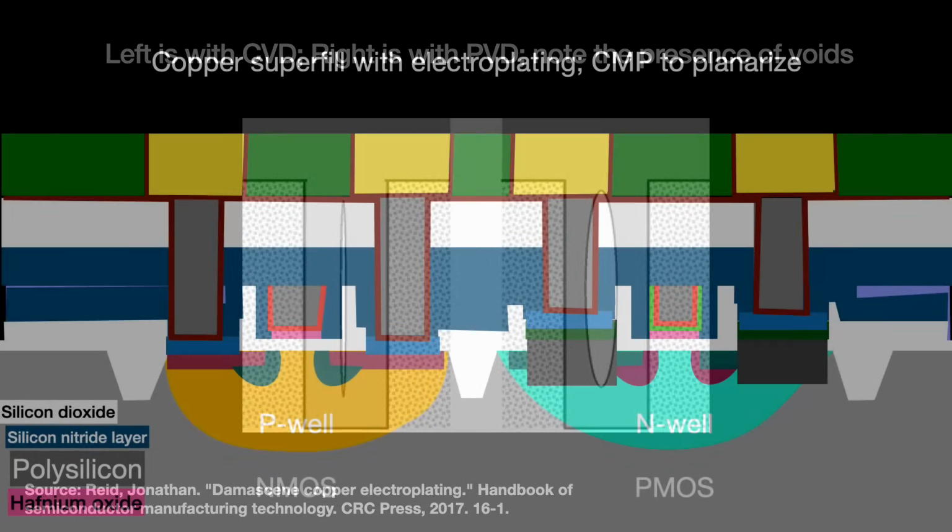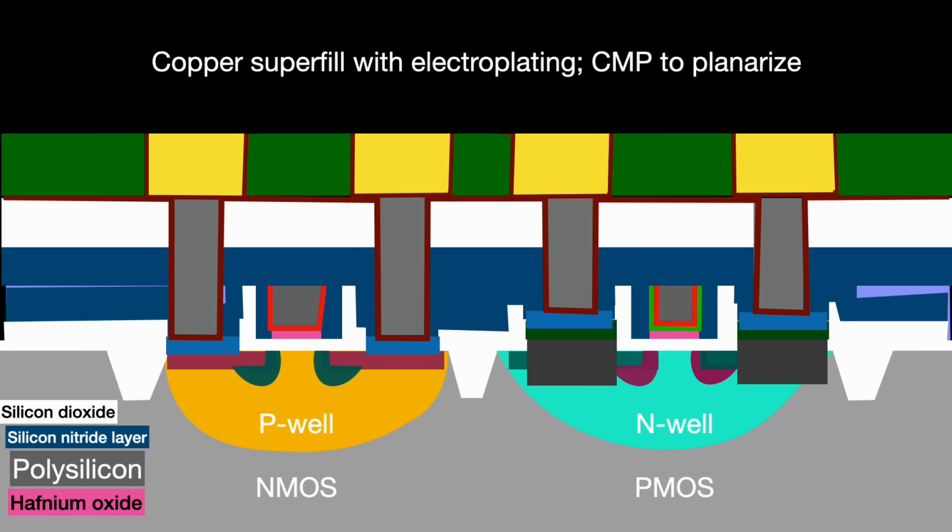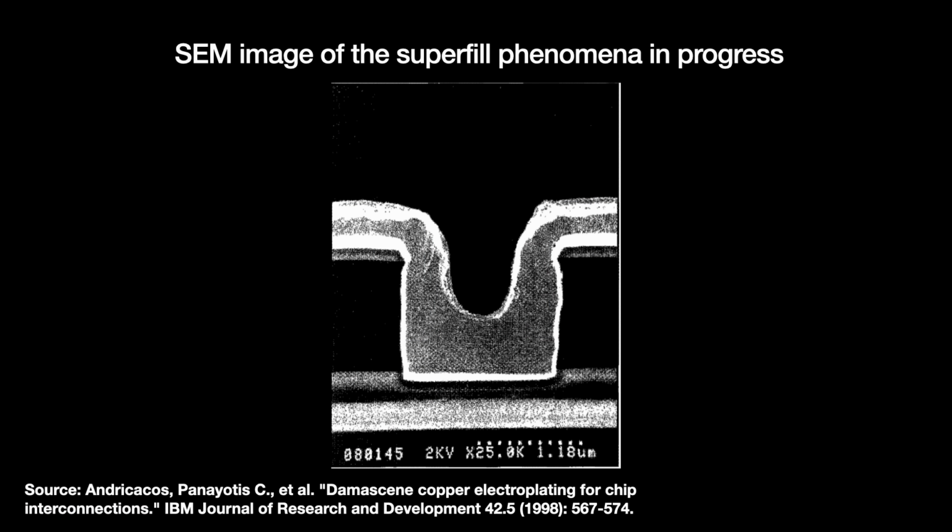Electroplating covers the whole surface with copper, so we need to use CMP to grind away the excess copper and leave behind our completed metal layer of interconnect trenches filled with high-quality copper. We're done. Further steps will include more metal layers stacked on top, produced with depositing an ILD layer, patterning with lithography, etch with an anisotropic etch, and more copper interconnecting. But otherwise, we're done. Rejoice.